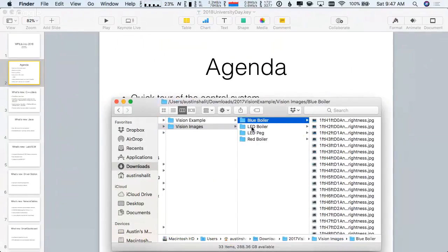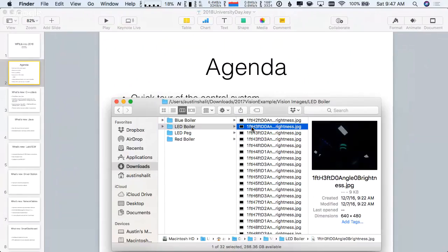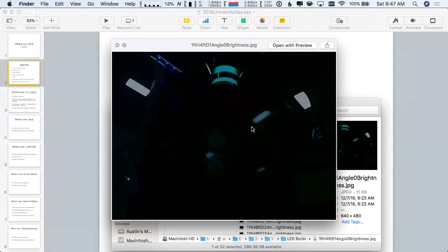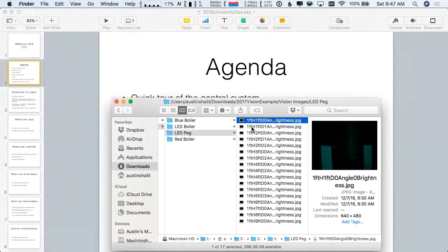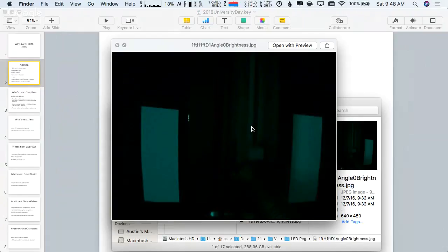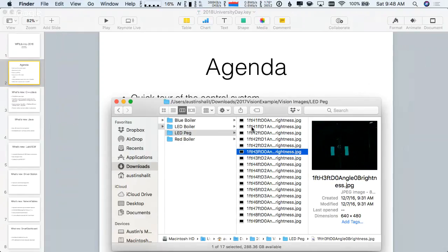If you have a camera on the robot, like a little USB camera, and you put a ring light around it, one of these automotive tail light ring lights, which you can get for like $6 or $7, then it lights up the retroreflective tape, and you don't see anything else in the images. Here's what the images look like. This is an image fresh off the camera with the ring light, and that's what the robot sees in that case. And so you write vision programs to do that.